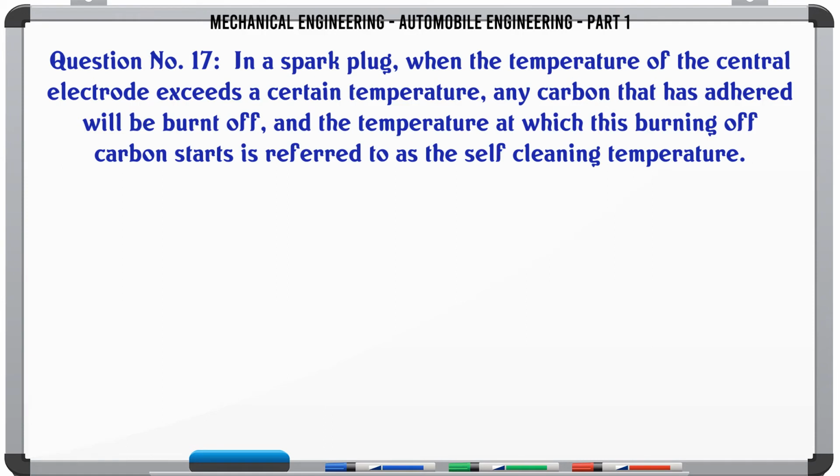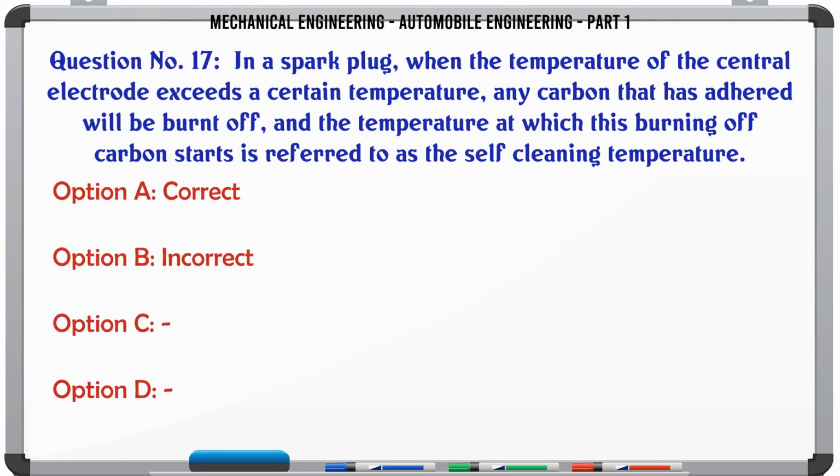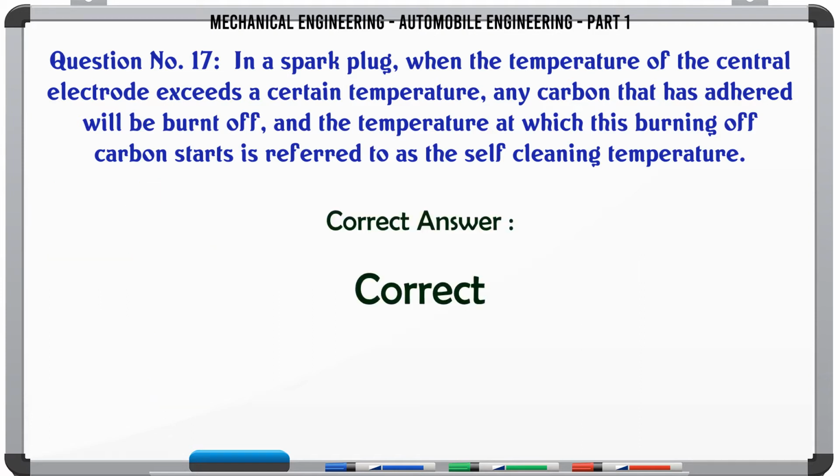In a spark plug, when the temperature of the central electrode exceeds a certain temperature, any carbon that has adhered will be burnt off, and the temperature at which this burning of carbon starts is referred to as the self-cleaning temperature. A. correct, B. incorrect, C. D. The correct answer is correct.